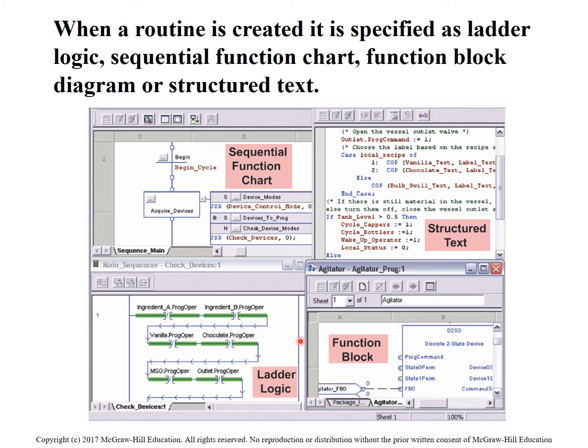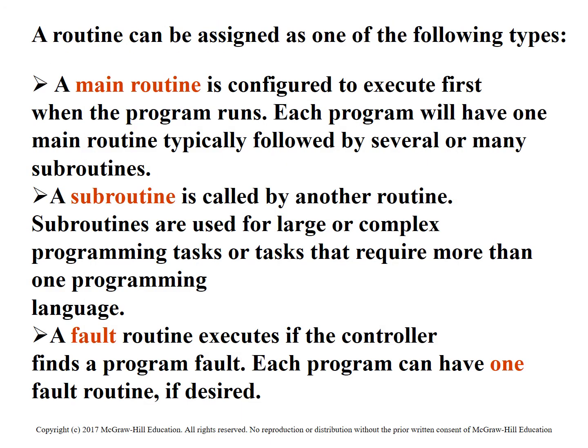But nowadays, I think we're still going to see a lot of the ladder logic, and then eventually we'll see more and more structured text as young people prefer to use structured text over the ladder. So, kind of a recap: the main routine executes first, then the subroutine, and then the fault routine executes afterwards.